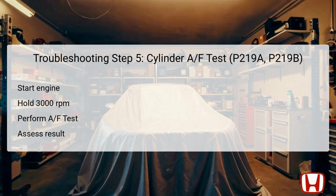Similar to the previous tests, ensure the AC is off and all other electrical loads are disconnected to maintain consistent conditions. After achieving stable engine speed, perform the cylinder AF test 3 times using the HDS in the inspection menu. An OK result would indicate an intermittent issue within the air-fuel adjustments of the system.